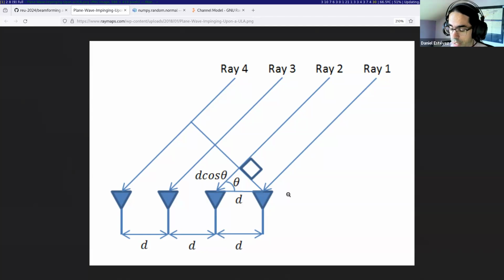Then what we can do is to beamform, so that will give us a much narrower beam by combining the signal from all of the antennas in the array. But since that is a digital process, we can do it as many times as we have computing power for that. And you can imagine, for example, if we are doing a SETI search inside this 1/4 of a degree area where the antennas are aiming, there might be many interesting stars that we want to observe.